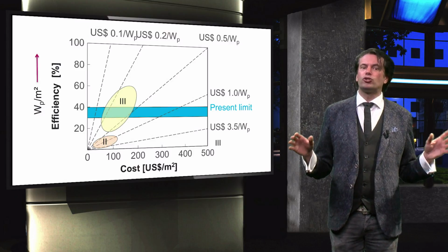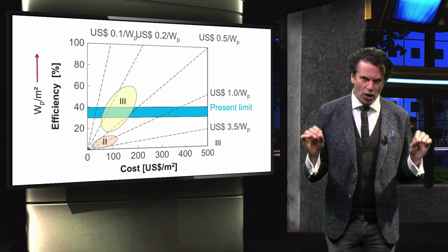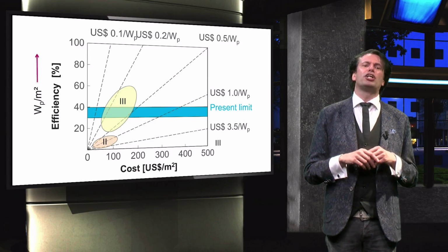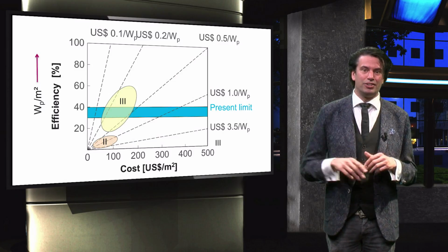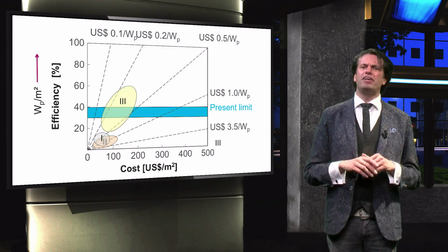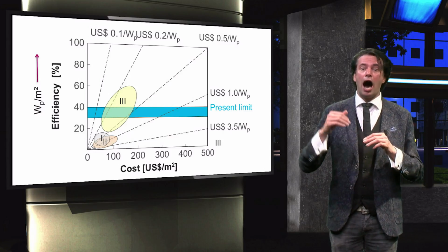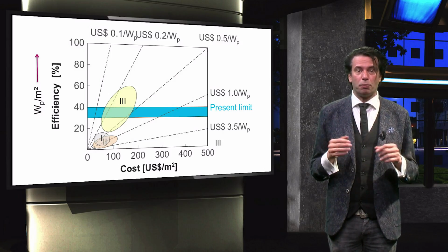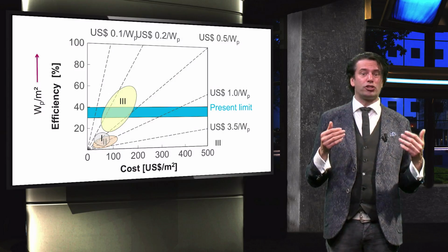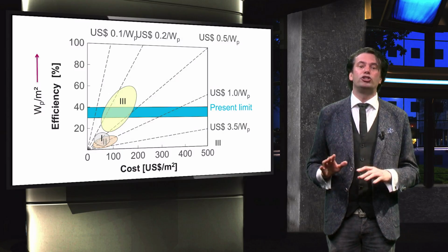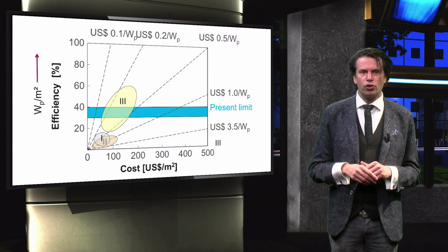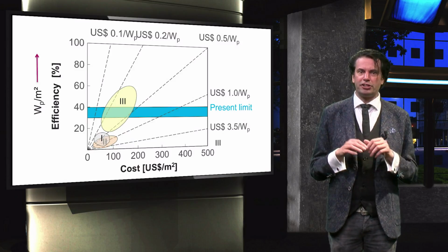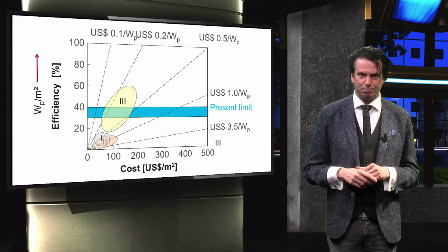The blue area represents the so-called Shockley-Queisser limit. The definition of the third generation PV technology is based on solar cell concepts which try to tackle the Shockley-Queisser limit. So third generation PV technology would be solar cells with higher conversion efficiencies in reference to the first and second generation, while the cost price of the materials and processing techniques used to process the third generation solar cells are expected to be cheap. The third generation solar cell technology was expected to overlap with the steepest dashed lines in this graph, meaning that the third generation technology would have the lowest cost price per watt peak.